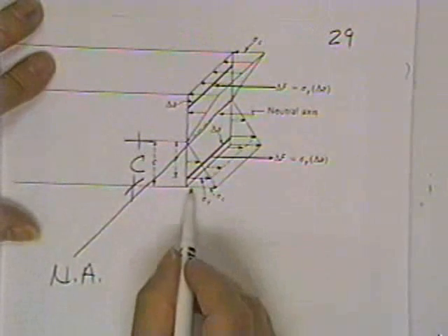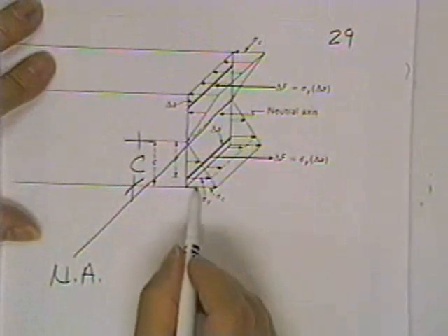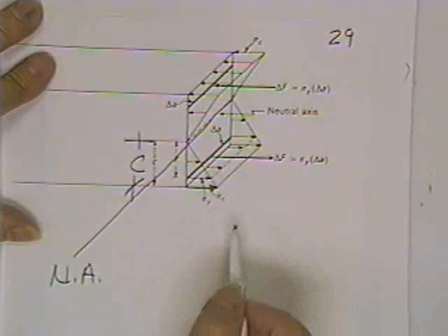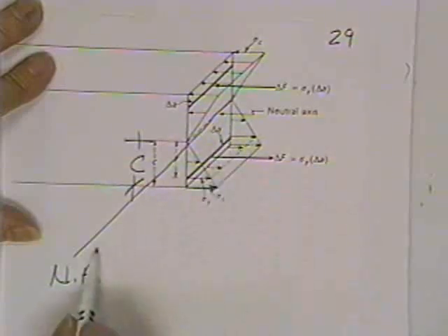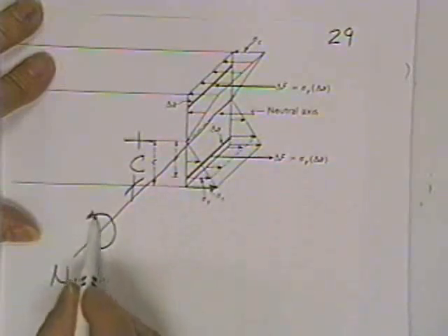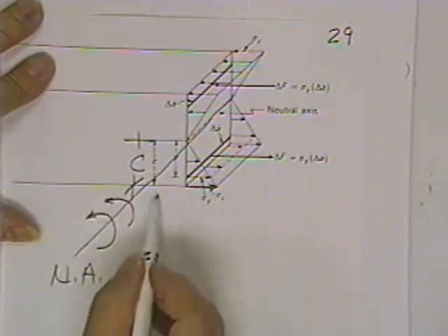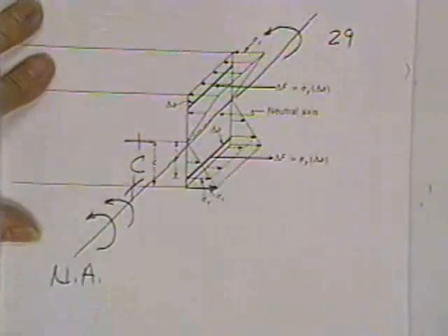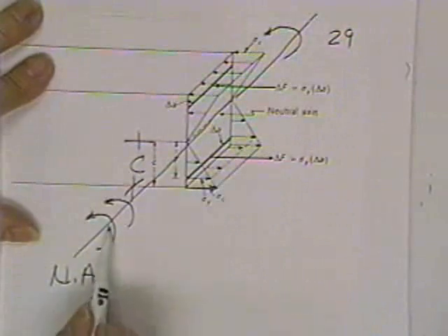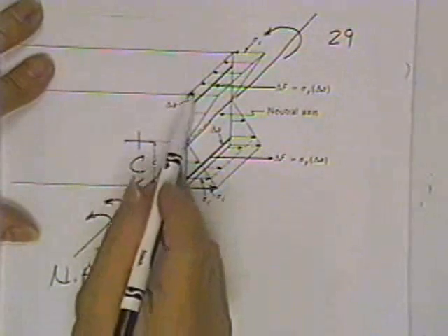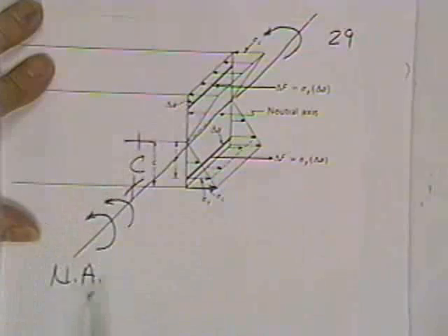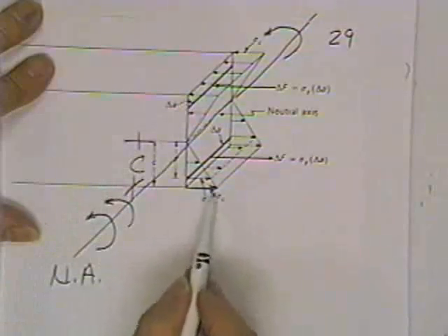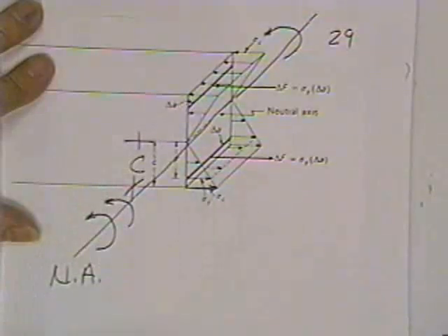Here are your stresses on the outside fiber. You'll notice that they are biggest on the outside fiber. This particular beam is being bent like that. And the reason I know is because these little arrows are banging into this surface, causing compression arrows on the top, causing stretching or tensile arrows, stresses on the bottom.